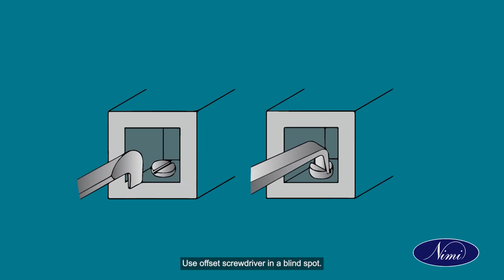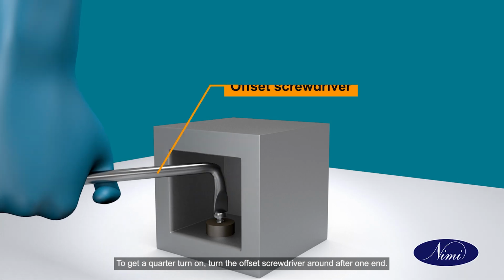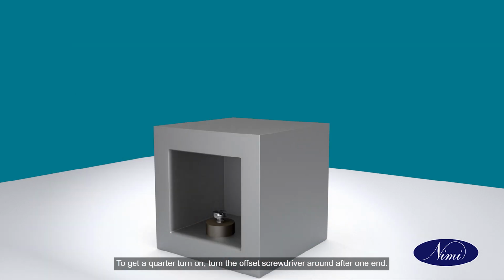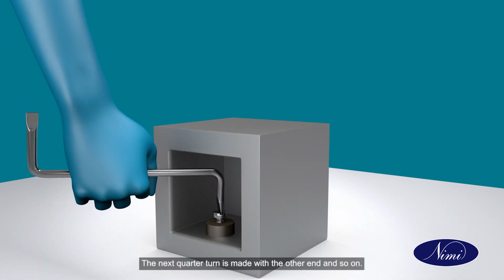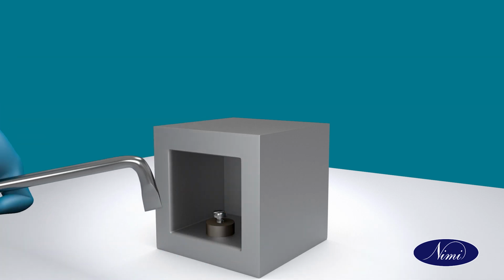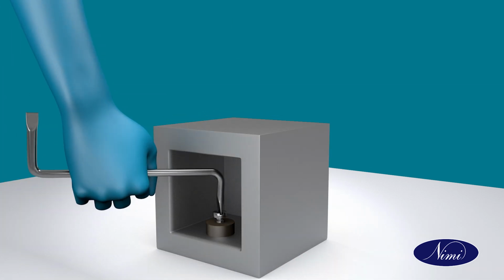Use an offset screwdriver in a blind spot. To get a quarter turn on, turn the offset screwdriver around after one end. The next quarter turn is made with the other end, and so on. As you keep turning, press the tip into the slot.